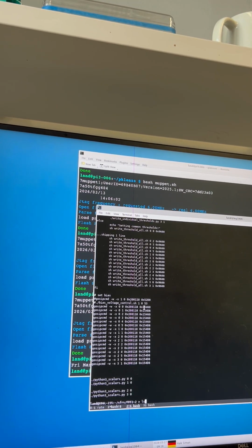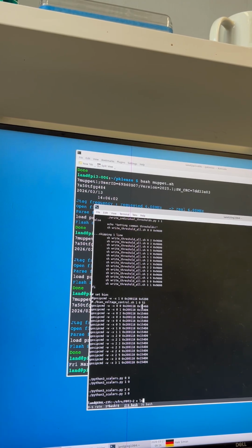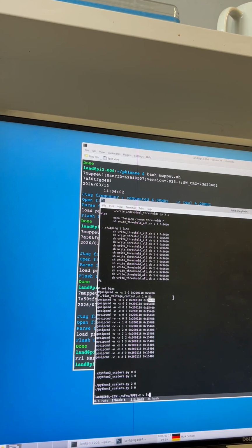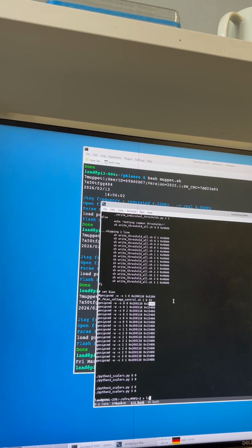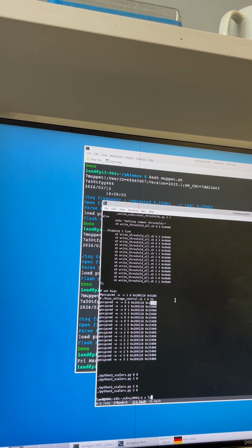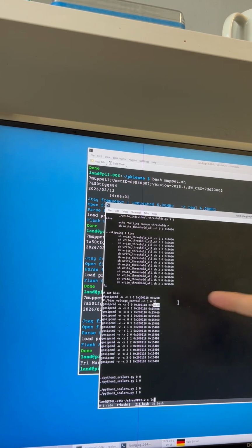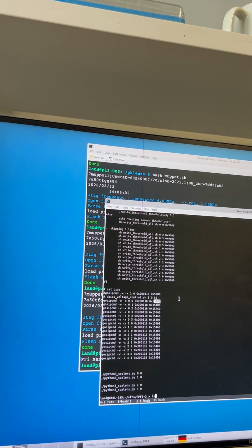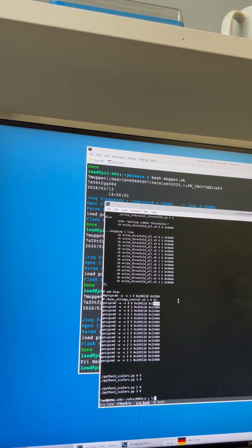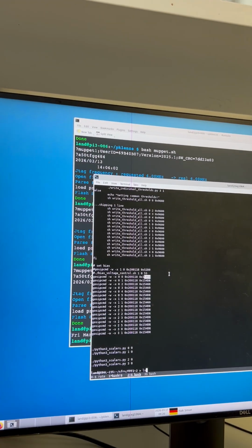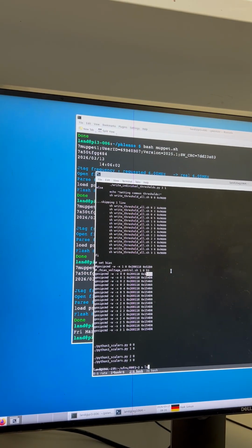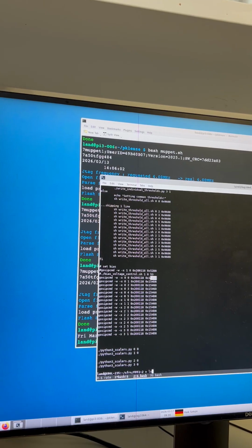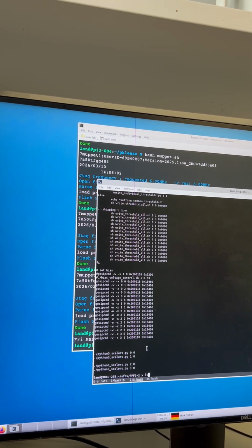The first number here is always 1, and then this second number here is the hex number of the bias divided by 400. So if I want to have 53 volt, I have to multiply, I think, with 400 and then write it in a hex number in here. And that's it. So we need to invert the signal, write a threshold, and set the bias. And these are the slow controls.